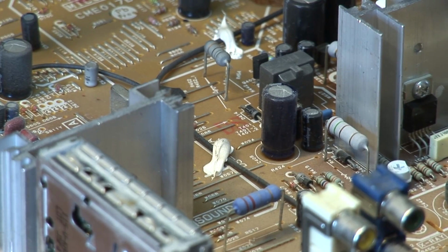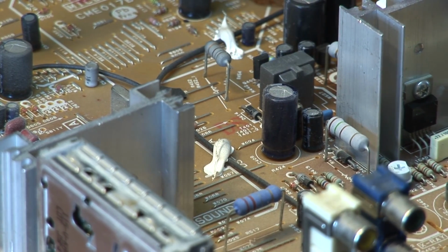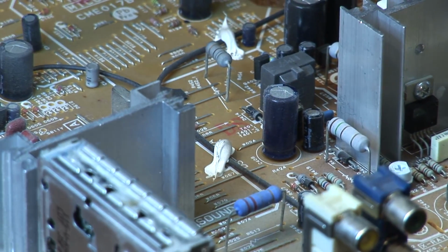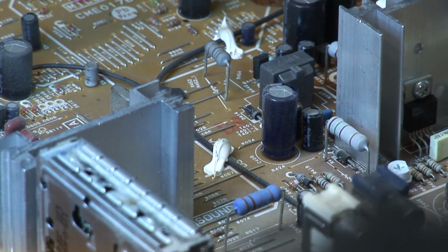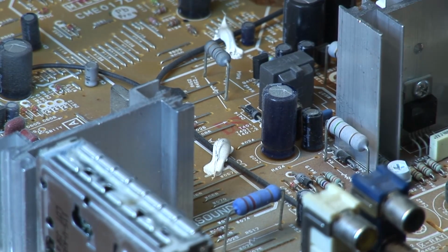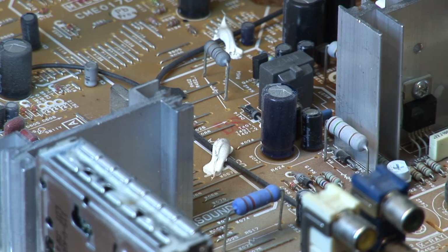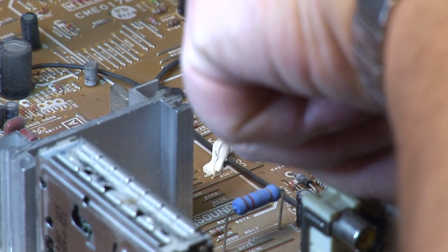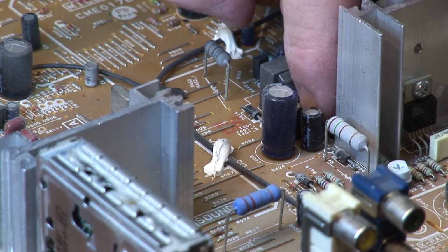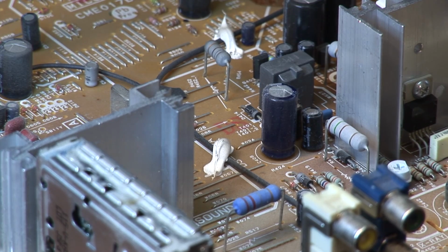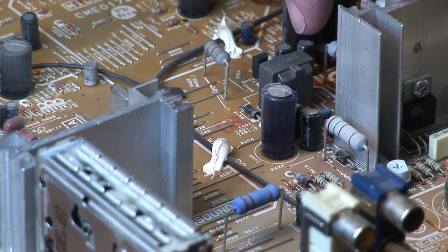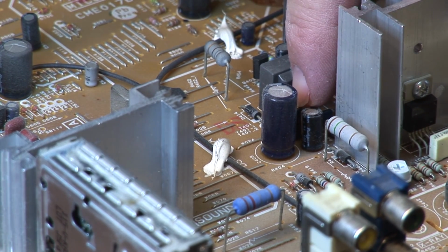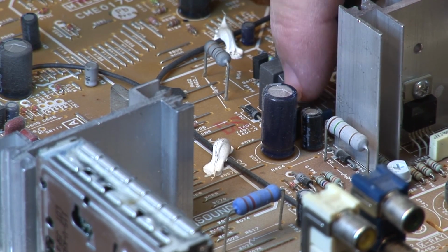So the two capacitors I was scoping is these two down in here. That one and that one. These two. Can barely see this thing. It's not that it's dusty, it's just awkward. C406 and C407. This one's C408. C406 and 407, these two little small buggers in behind here, those are the ones, and it's the small one here, actually 406, the one in the back, this is the one that I was getting the most amount of distortion on. So that's the first one I'm going to check.